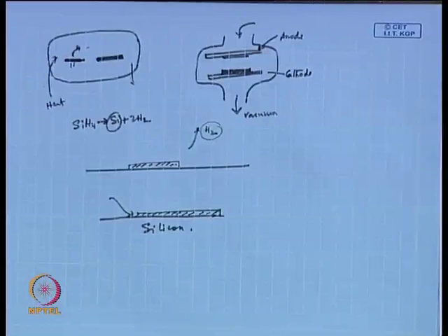So, if we need to do that, you have to ensure that the silicon atom is there when you want it, in the right quantity. If you have a mass transfer limitation, one silicon could diffuse, but there was a concentration gradient, so silicon could not reach there. If such a situation comes up, then it will not be straightforward. In that case the crystalline arrangement will be imperfect. You will not have exactly those 2 face centered cubic lattices interpenetrated in the way they are supposed to be.